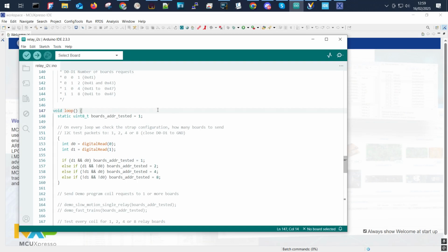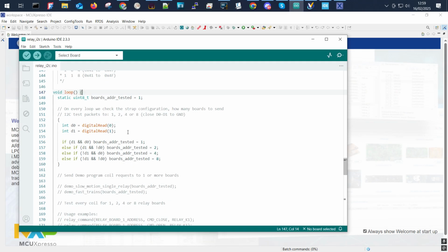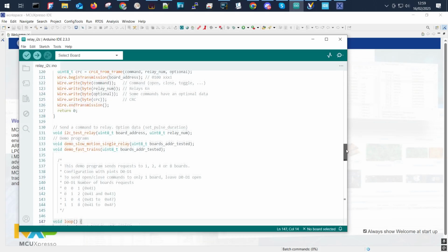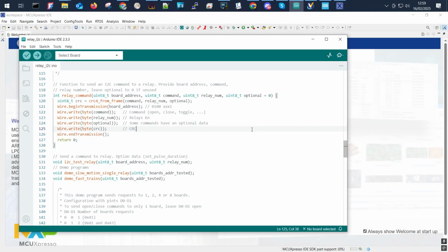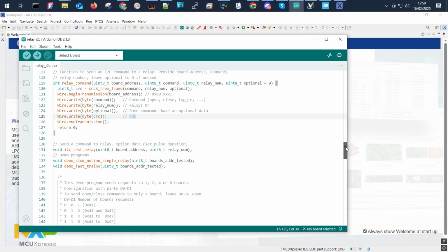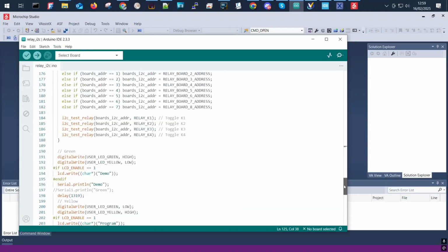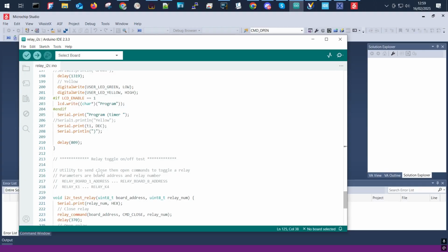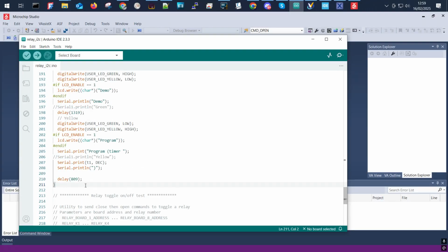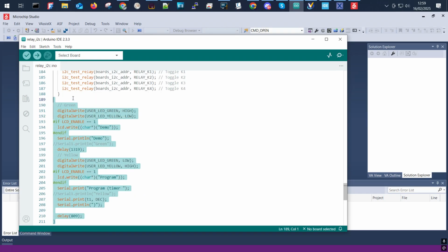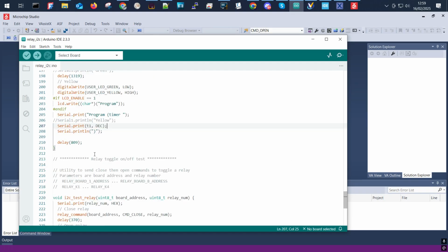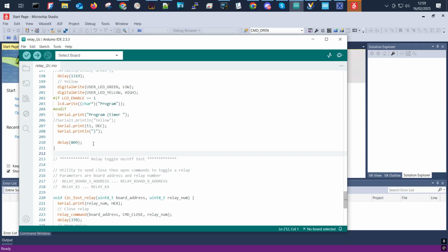Some are prefixed. For example, the timer can be used for the millis function. It can be programmed in a particular way, and the clocks can also be programmed in a particular way. So we are using the IDE with some of its limitations. That is, the processor and the library were implemented on a particular configuration, and we might lose a little bit of performance for some code we want to do.